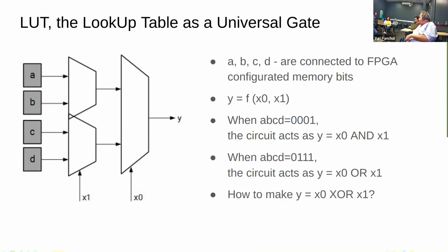Yes, it's purely for functional verification. Companies making emulators either use FPGAs, like Zebu uses Xilinx high-end UltraScale FPGAs, or, like Mentor Graphics Veloce, they use an FPGA-like ASIC, which is a chip that behaves sort of like an FPGA, but it is a custom version of FPGA specifically for doing emulation.